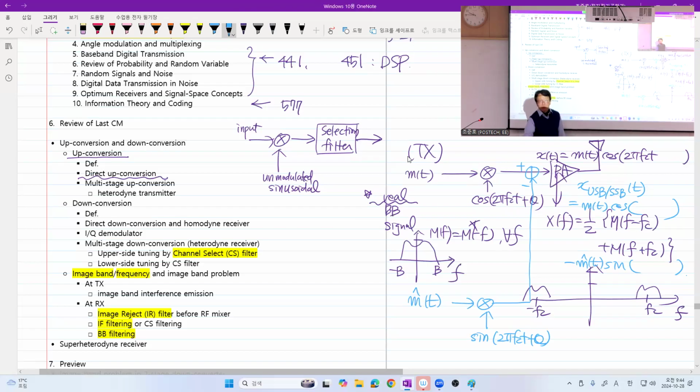Then what happens? You have self-interference between in-phase and quadrature phase components, and you don't want that. Usually, a lower frequency signal can be more easily generated with higher integrity. Here, integrity means the signal's accuracy compared to your desired target signal.